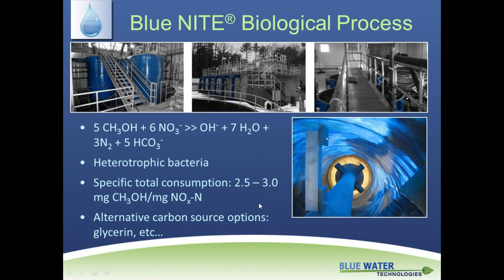In addition to our adsorptive processes for a lot of these industrial sites where we're removing metals, heavy metals, even some of these non-metals we've covered, we can also do biological processes within the same vessels, within the same treatment stage, because we get quite a bit of residence time within these vessels. We can add biological treatment considerations in a lot of these applications to remove things like nitrates.